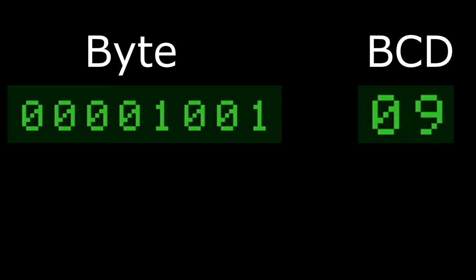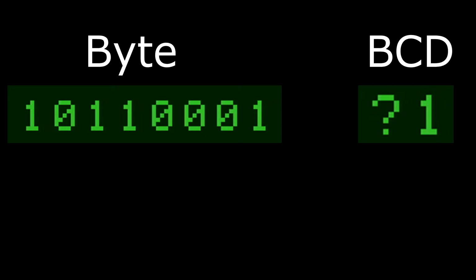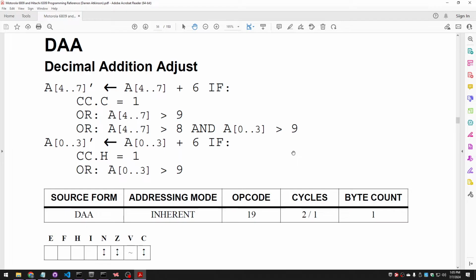Since we waste so many perfectly good values of bytes when we're using binary coded decimal, that tells us that binary coded decimal is in a way rather wasteful. If you're trying to encode numbers with the smallest possible amount of space, binary coded decimal is not the way to go. What support does the 6809 have for binary coded decimal?